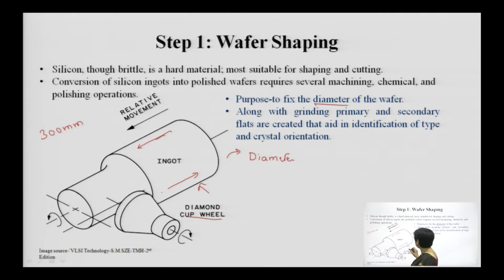Now, this is basically the grinding process. This grinding has to be uniform. Of course, there is going to be some loss at this point, because of grinding there will be some elimination of the edges. One more thing you have to remember is that beveling is also equally important, because during formation of the ingot, if there are stacking faults, there is every possibility.